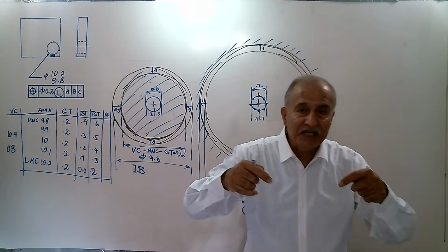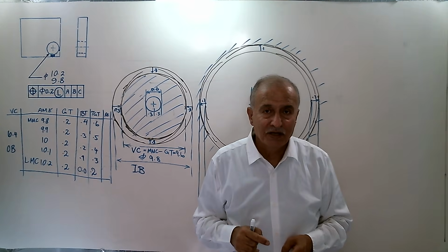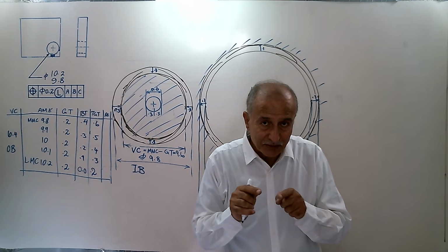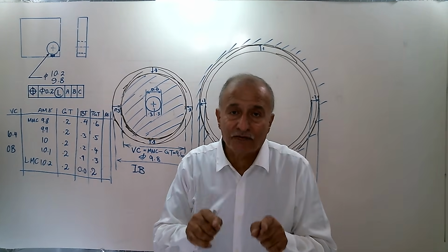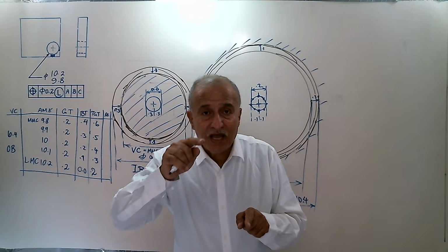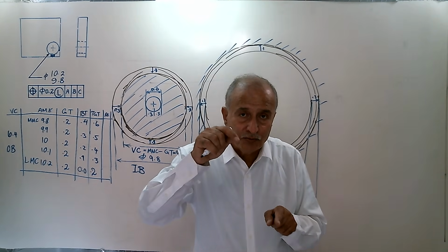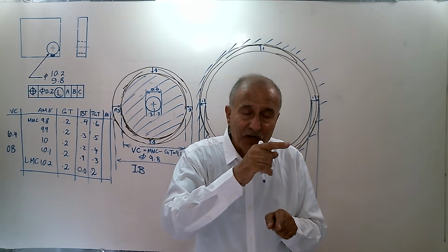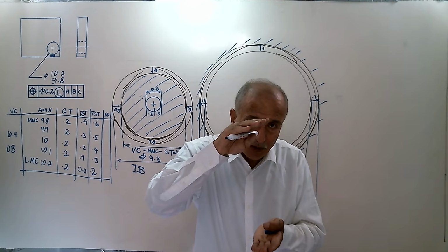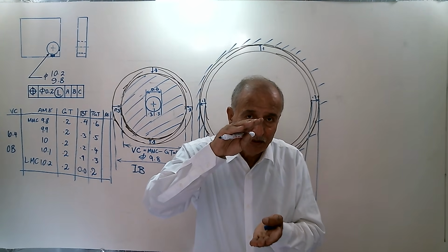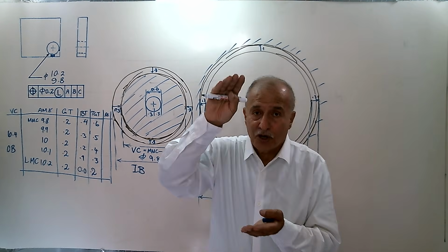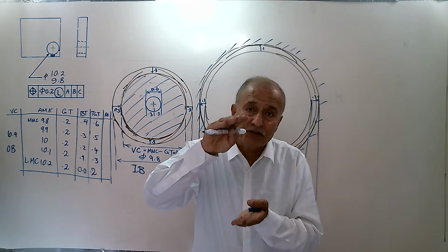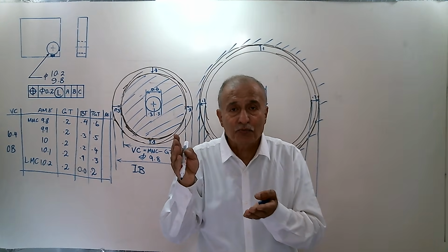We consider the inner border of the hole when you produce at MMC, smallest diameter of the hole, and you made a mistake, go 0.3 down or up or left or right, the hole comes down. One part holds 0.3 down. For another part, it's 0.3 upward. For another part, 0.3 to the left.